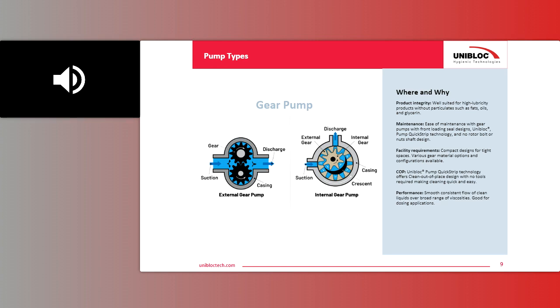Most of these pumps are on the medium to small size, so from a 1/2-inch up to maybe a 2-inch typically. So you don't have a wide range like on the previous slide on the rotary lobe pumps. They are a lower cost pump technology. There's only one driving shaft in this technology. And they're very repeatable on the output of the pump, or the displacement of the pump. So a lot of times they're used as dosing pumps to feed, because they're very consistent. You can actually give a fixed amount of liquid flow based on the speed of the pump.